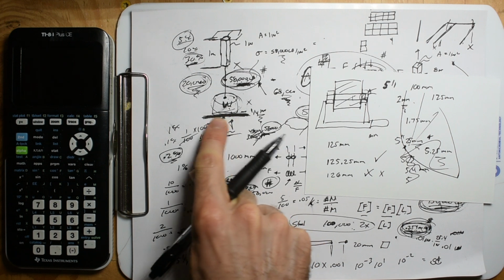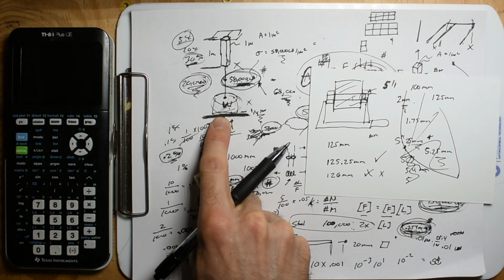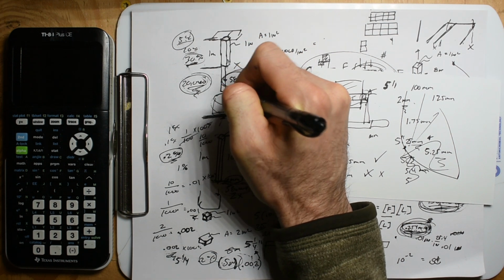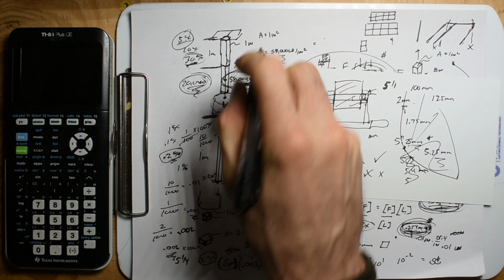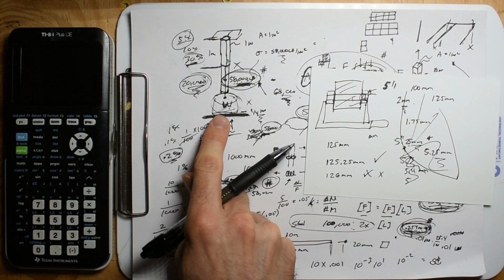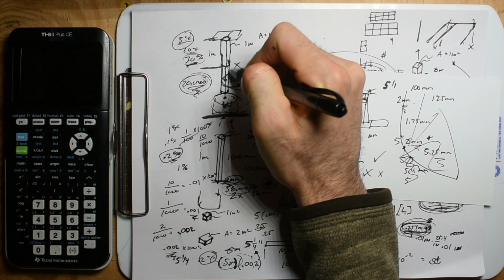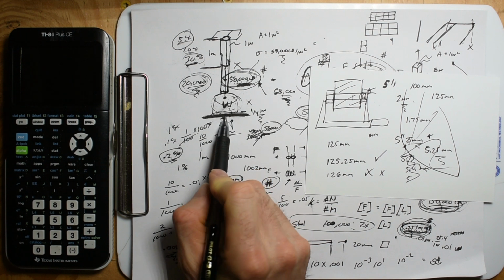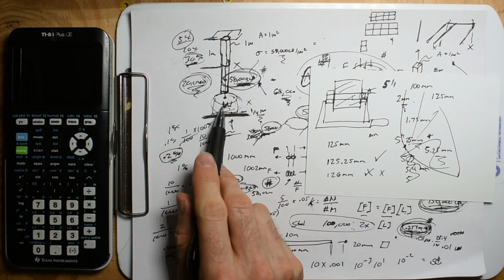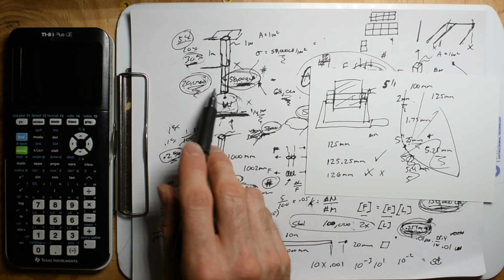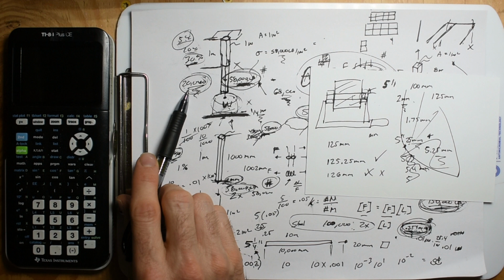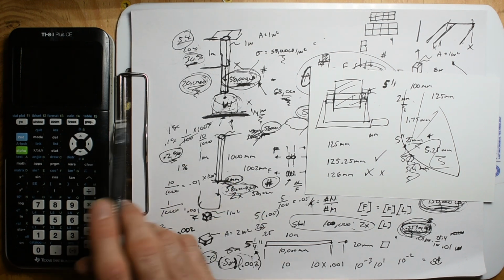Like we said, it's the same thing with this. Weight is a 1/4 inch off the ground. And we already know, yeah, nothing catastrophic from that. It's so fascinating that even this, you're just like, hey, I have this 1 meter bar, something super heavy, a 1/4 inch off the ground. I can load this up till its breaking point, just on the basis that I know that it can. I know that it can plastically stretch 5, 10, 30%, at least 5%, and so that gap's going to go away.